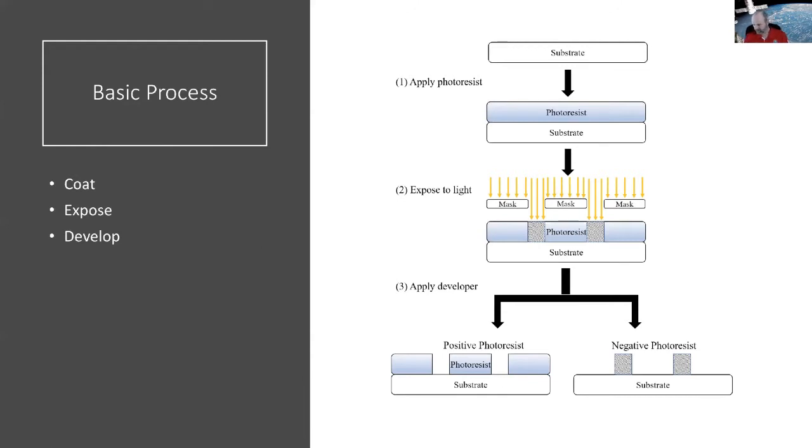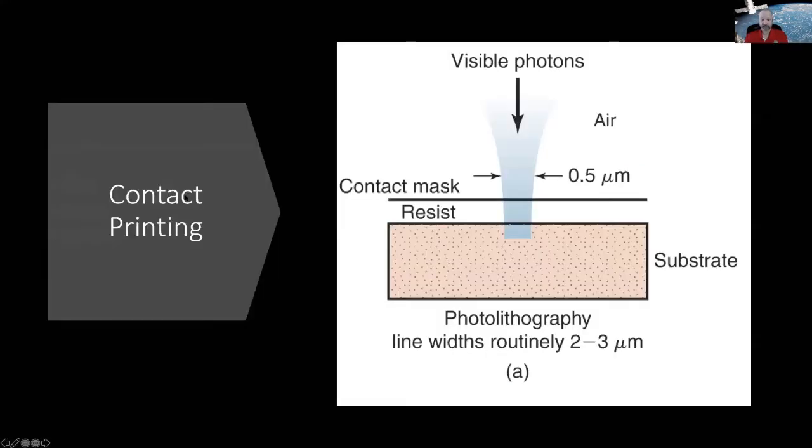Do you use a different mask for positive and negative photoresist? Yeah, it depends what you want to have remain on the wafer, so you might have the opposite image on your photo mask. On the left side, it's the positive photoresist, where we like to say what shows goes. Whatever's clear is what gets developed out, and whatever isn't won't get developed out. You can see the photoresist remaining on the surface is protecting what's underneath for the subsequent etches, and that'll become more apparent as we go through the process steps.